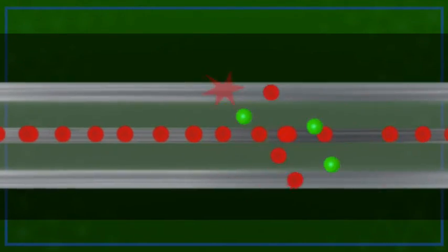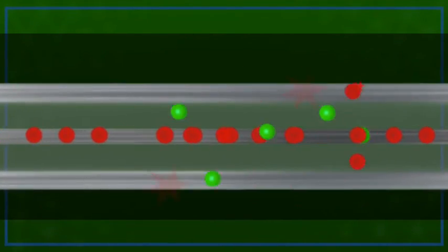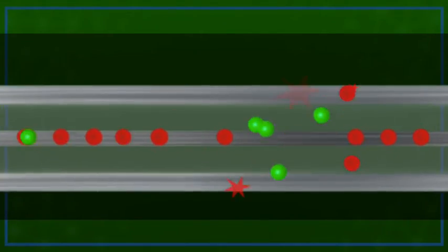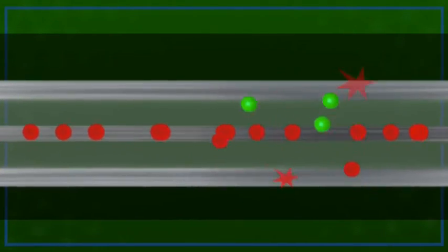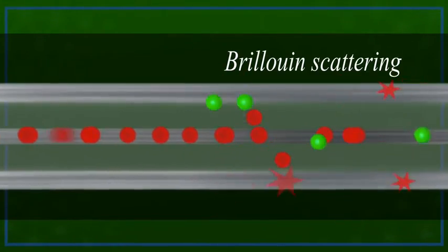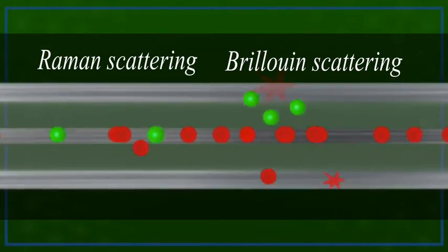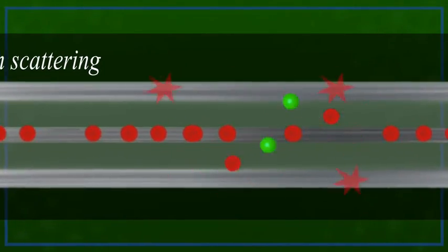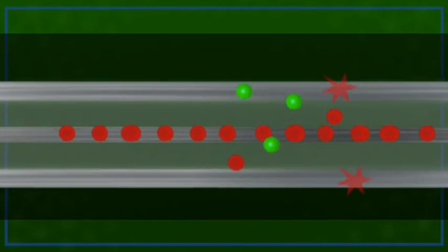Now we have created another situation, too much light. As power in the laser goes up beyond a few hundred watts, photons in the core start to behave differently, much like surging traffic on a congested highway. Nonlinear effects start to appear, such as Brillouin scattering and Raman scattering. The solution is the same as on a highway. We add more lanes.